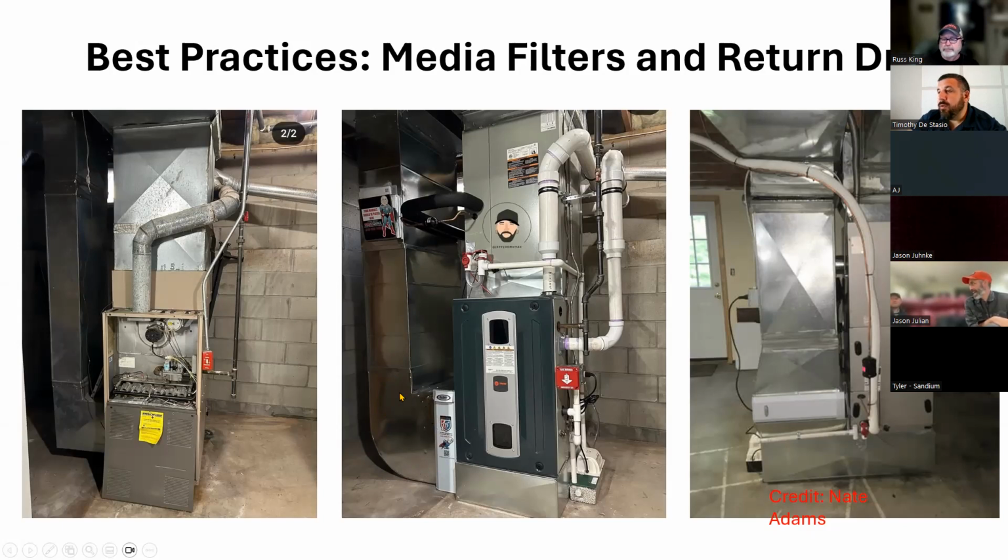If I had to choose between having a rounded throat here or a rounded heel here, a rounded throat is always better. It's okay if you're square here, but it's a lot better if you're rounded here. And again, using filter media, sizing up, a big old return drop. For the life of me, I do not understand why you see these little skinny return drops. They're just the worst thing. You can pick up a lot of performance just selling a media filter and a larger drop.